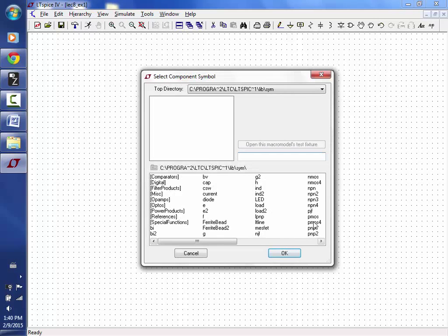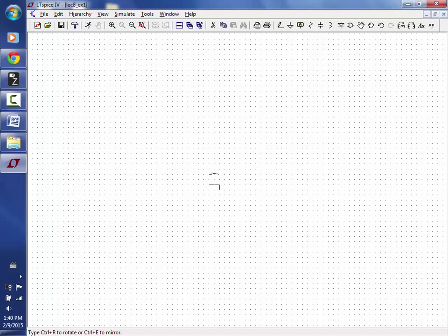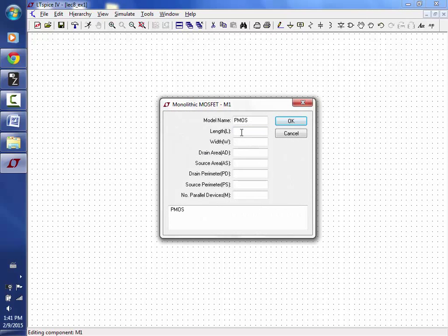All right, so let's go grab our PMOS 4. And then if you recall, for some reason, LTspice puts the source at the bottom. You don't need to do this because source and drain are interchangeable, but I'm going to do the following so that the source is at the top. Now I've done this 3 times now, and I don't want to feel pain, so I'm going to copy this MOSFET as much as I can. I'm going to call this 1U, not 1. That's where I'll inflict pain on myself. And then I'll call this P underscore 1U.